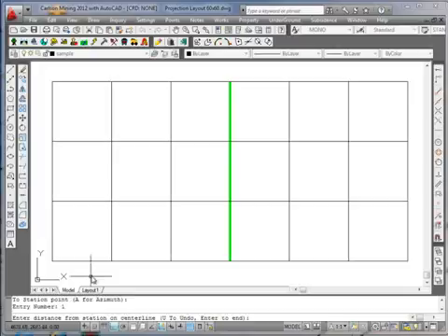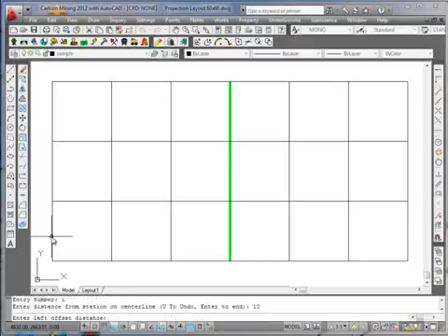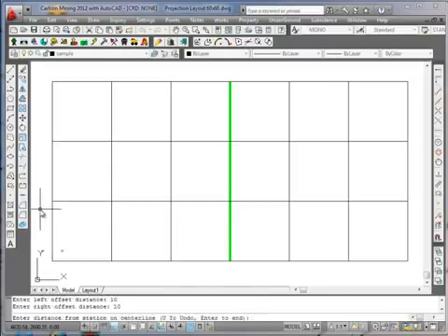And now we're prompted for the distance from the station on the center line, which means from the point that we start, how far up the center line do we want to go, and I'll go 10 units, 10 feet. And then enter the left offset, which I'll also use as 10 feet, and then the right for 10 feet. And we'll see there's a point here and a point here known as an offset. And if we advance these up a little bit,